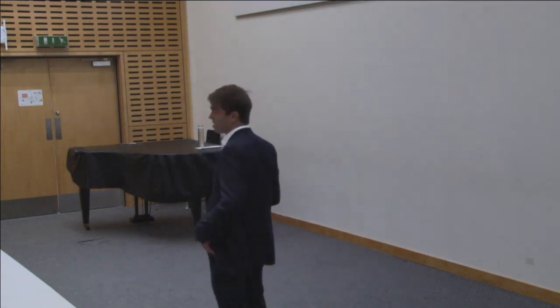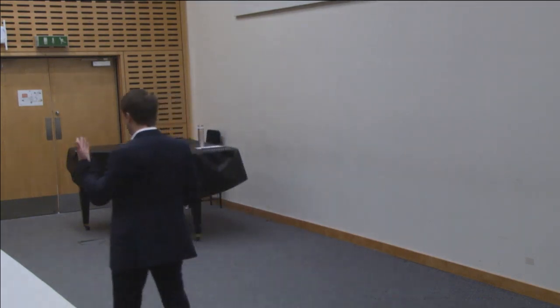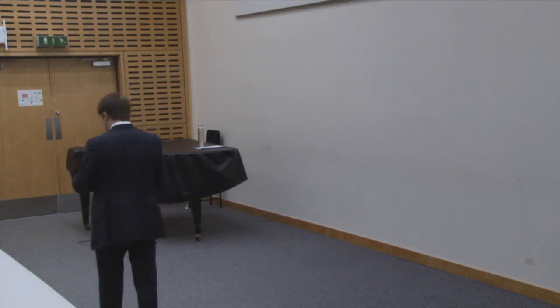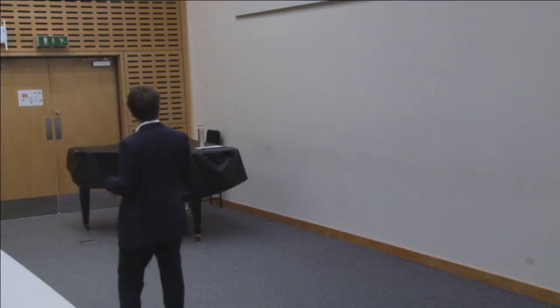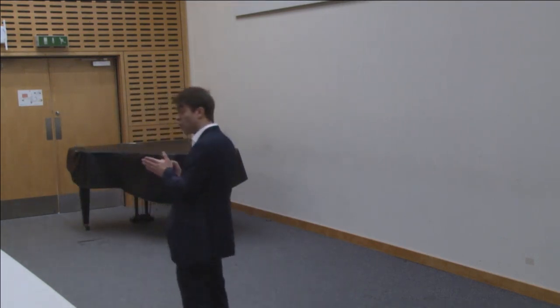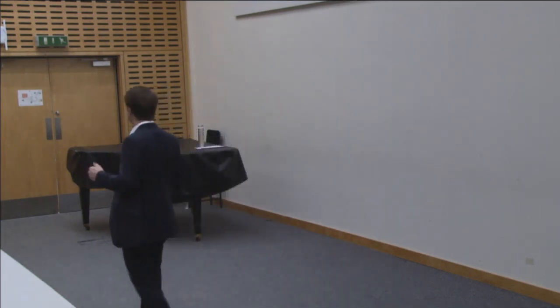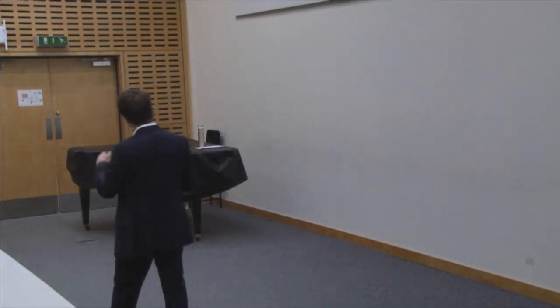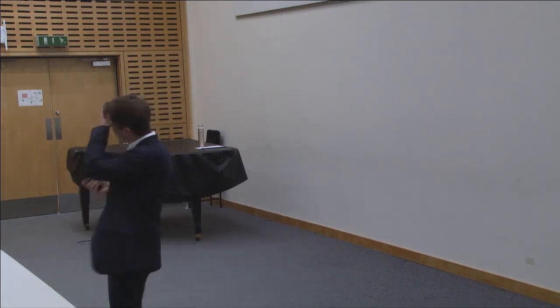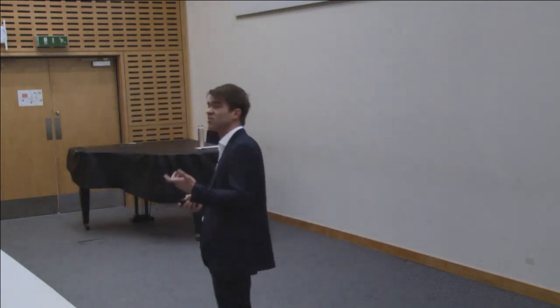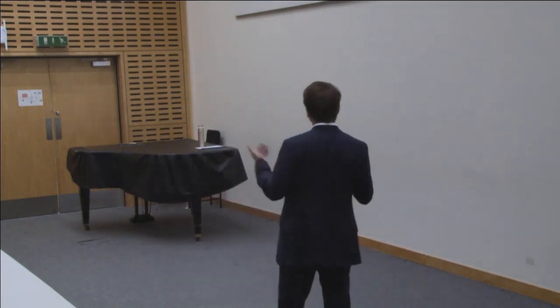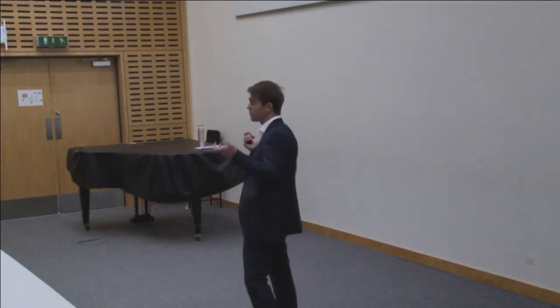You have the presence of lubricant, which can create additional factors, such as the entrapment of lubricant in the surface-breaking crack, which can accelerate propagation. Crack closure and rubbing, which means that it's very difficult to work out stress intensity factors, as you will see later. And the post-failure damage is significant, so it's actually difficult to establish root causes of the failures. So it's difficult to study, but we try.